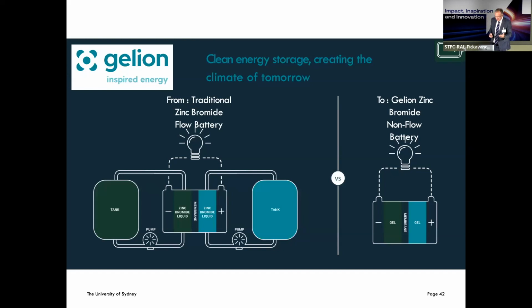So the breakthrough was that I worked out all the issues that we get that need flow: hydrogen evolution, pH drift, also segregation. All has to do with the bromine and bromide not staying where it's supposed to stay inside the battery. The gel was able to dynamically accommodate the change from bromine to bromide and back and keep it locked where it's supposed to be. And that enabled the whole design to be changed, and that then enabled all sorts of other concepts and implementations down the line.